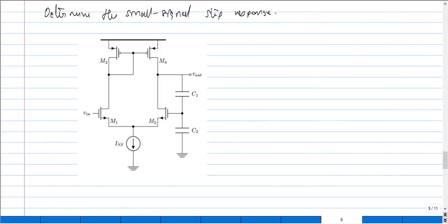Again, this entire circuit we can model in terms of a simple amplifier. I have my Vin here, and this amplifier has a gain, so instead of drawing an amplifier, I model it as a voltage controlled voltage source, which is gain times the input, which I take as V1. Plus and minus, and this gain times V1 is the potential that I have here.